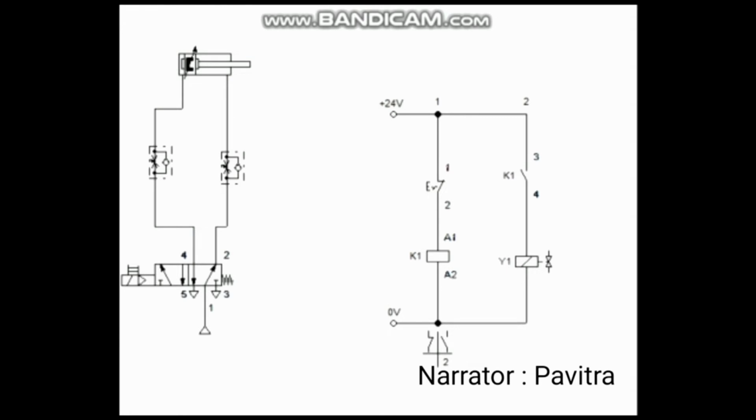In the second figure, circuit control for sustained output using detent switch. The output for push button and detent switch was different because these switches keep the switch position, and the switch position remains unchanged until a new switch position is selected. They are designed to be normally closed, normally open, or changeover switch.